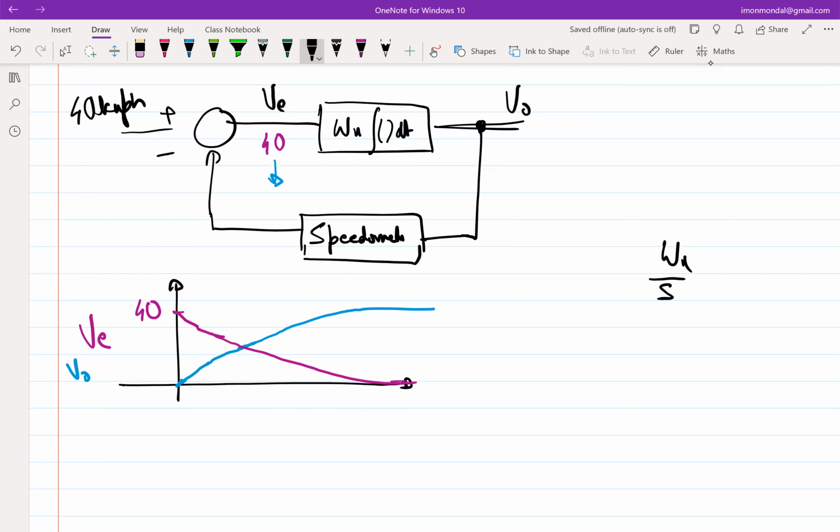Another design constraint that designers will face, as you'll also see in upcoming lectures, is that we not only want a negative feedback loop where you get good enough gain, you also want to reach the output at as high a speed as possible, which means you desire omega u to be as high as possible. Does that make sense?